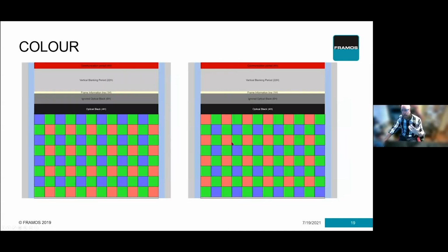This is a very easy mistake to make, and it also happens a lot in commissioning where there are a lot of additional modes. That's because the image sensor, depending on which one you're using and how you read it out, as you change resolution, as you drop pixels from above and below and left to right, or read it upside down or back to front, you will end up getting your Bayer pixel array where the first pixel will be blue in one instance and red in another. Therefore, when you apply your debayering, you will not get the colors you're anticipating. You'll get some crazy looking colors.